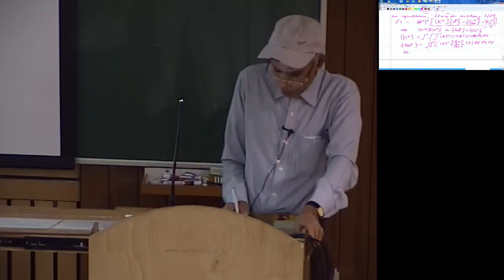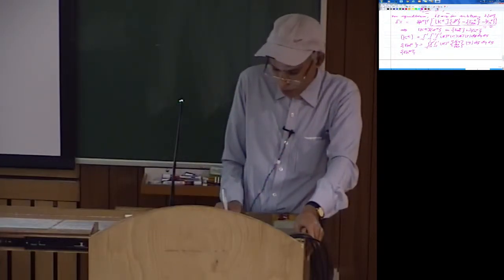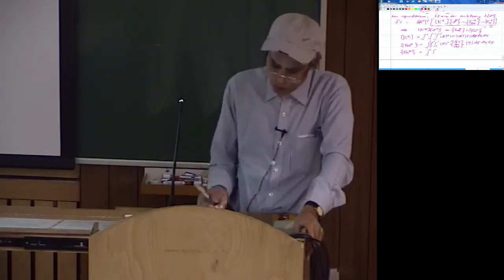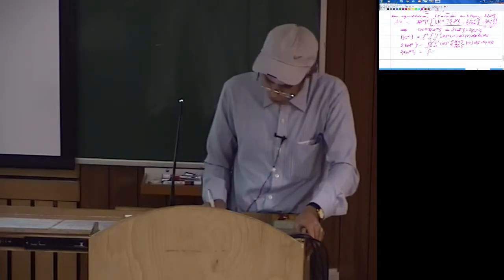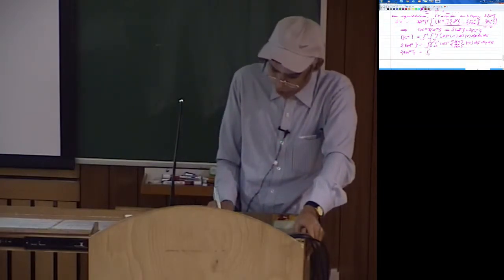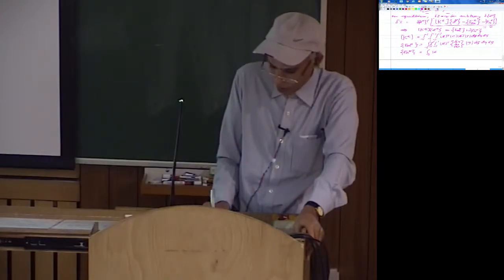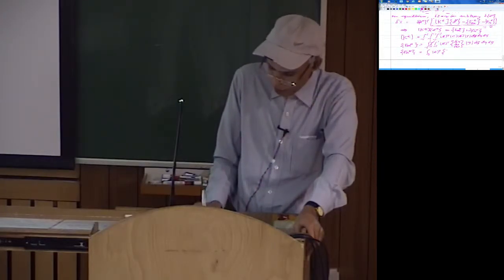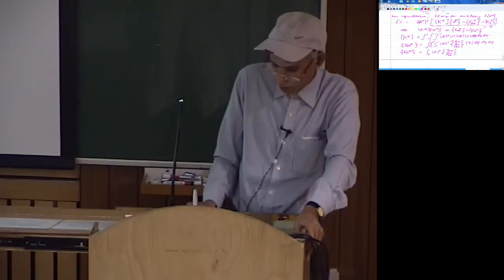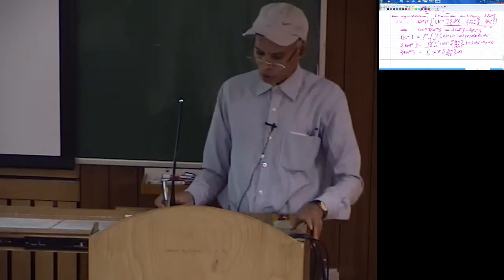And F internal for the element is again in a similar manner, -1 to, this I will leave as it is, not minus, because it is the surface integral. So depending on the surface you will have to actually evaluate, so I will just leave it as a surface integral. It is H transpose and then Tnx, Tny and Tnz ds. This has to be evaluated of course properly.